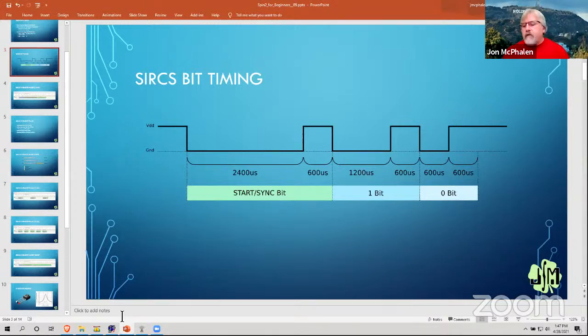I have one of the programs that will let you point any Sony remote at it, and it will tell you the bit count, and then it will show you the packet bits, the same as in the protocol analyzer that you saw in the logic analyzer. When you saw those spelled out, we can do that too, but we have to know how many bits we received. We do that by watching this period here.